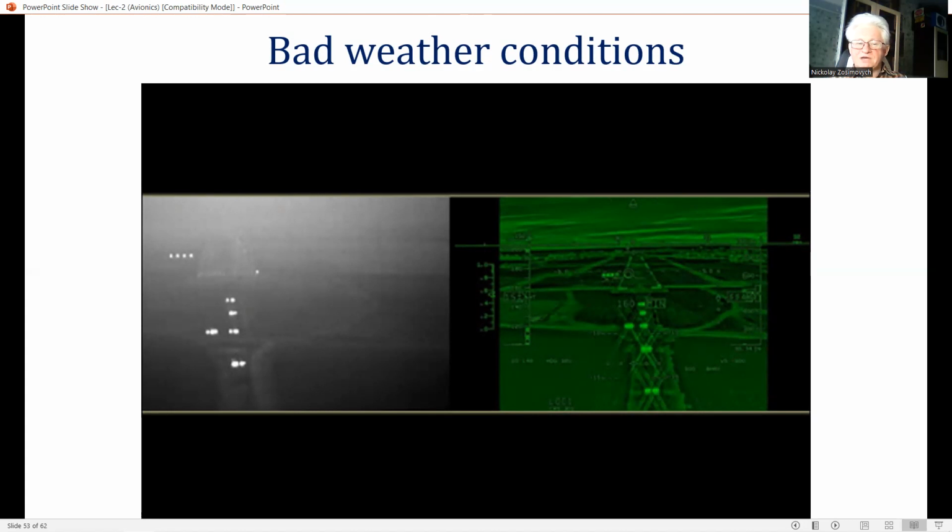The 35 GHz radar sensor, however, was able to operate successfully under all weather conditions and enable a synthetic picture of the runway to be generated from the processed radar image at a range of 2 to 2.5 miles. The pilots were able to identify the runway on which they intended to land at a range of about 1.7 miles.